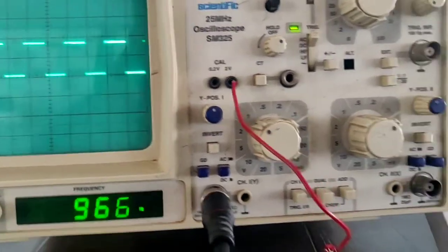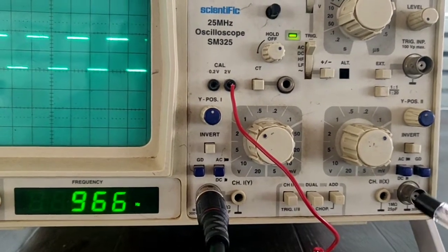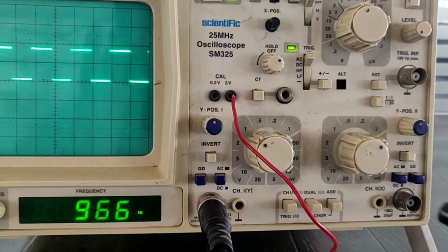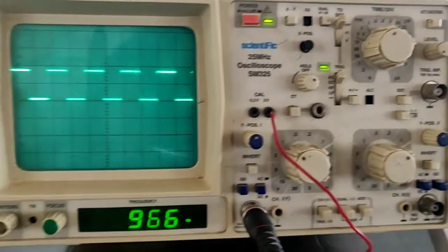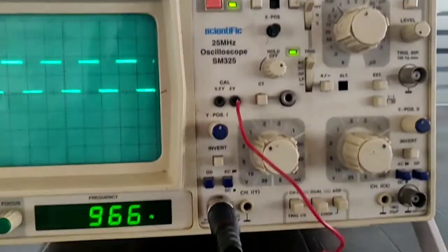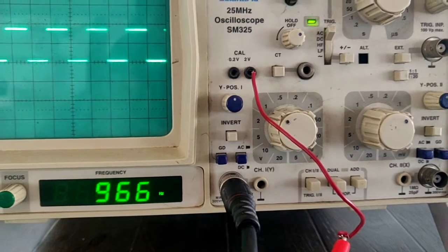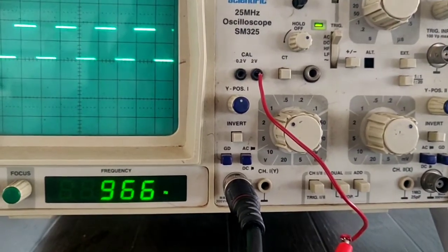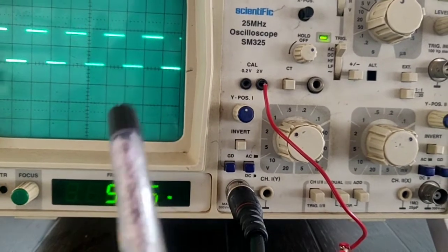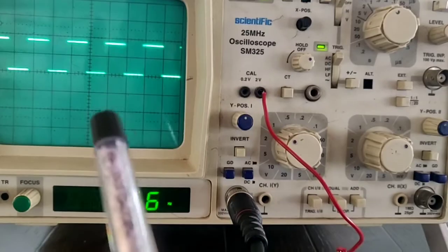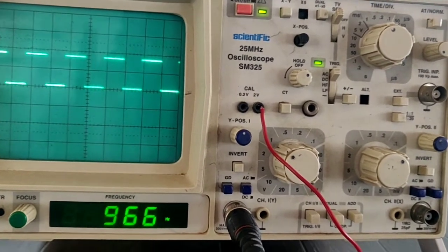Do not connect, because we have different BNC connectors here. I have observed that many students will connect probe 1 here, 2, and if you observe one more probe somewhere here, there also they will insert it. So don't. Just select the first channel, connect it to the first channel only, and test this probe. If the probe exactly matches the calibration, that shows the CRO is calibrated properly.